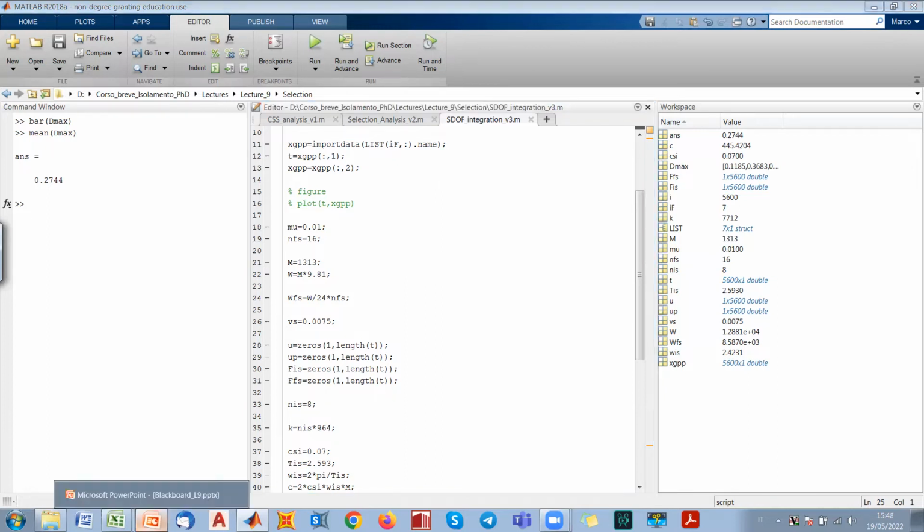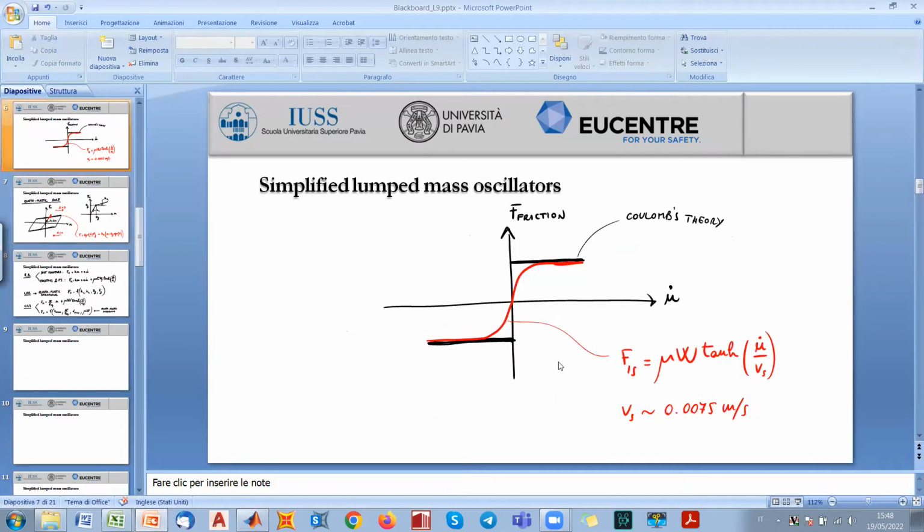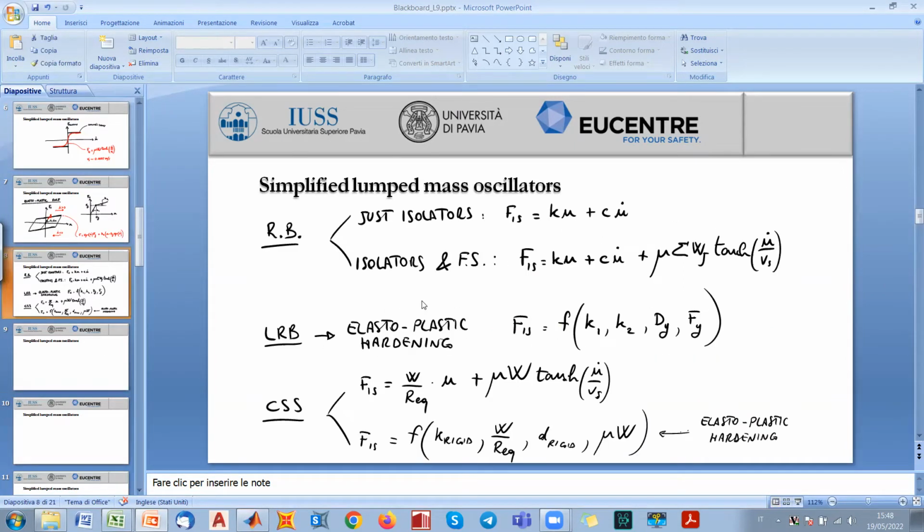And for sure, I've just shown these rules for isolated systems, but these can be generally used for any kind of system. For instance, the elastoplastic with hardening hysteretic loop can be adopted for generally any kind of application whenever you need the definition of a yielding point and a post-yielding stiffness. And also the frictional response can be used for frictional dampers and so on. So these are useful for any kind of application whenever you have to model such a typology of hysteresis, I mean.